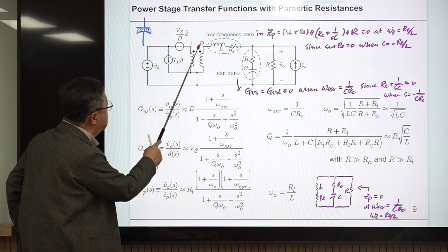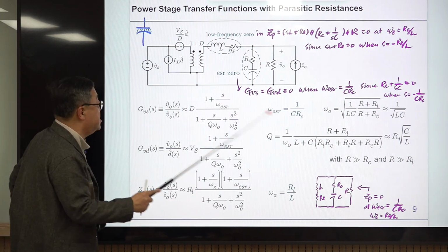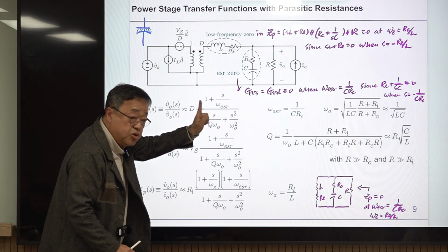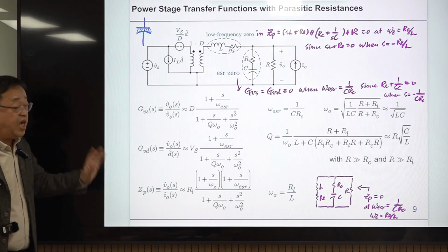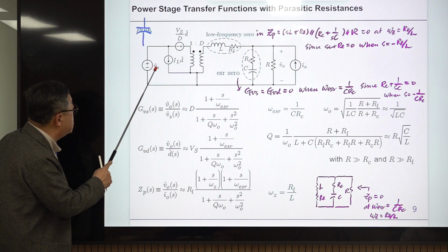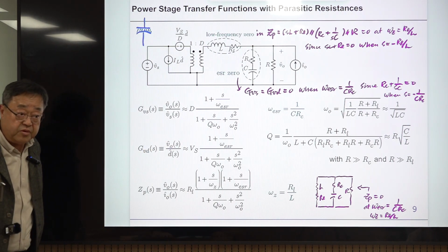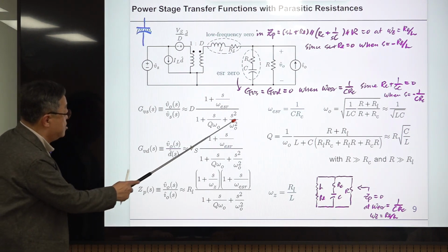That's the low frequency gain, because at low frequencies, at DC, s is 0, so those terms are gone. They all become 1. Then you have D, so the DC gain is coming first. Then you have D times Vs coming here. And this one is what? Just voltage division. You can easily evaluate this and put it in this form.